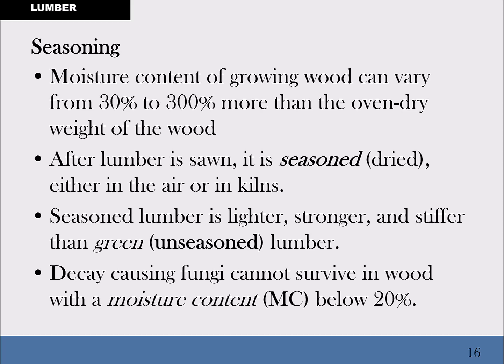So what we normally try to do, our best practice in general, from the beginning of time, is to keep the moisture content below 20%. And what that really means is 19% has been the standard forever. But in the last, I want to say, decade or so, which is still a long time, that standard has kind of moved down to 15%.